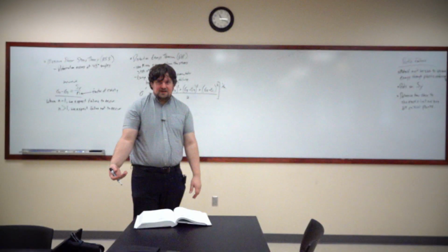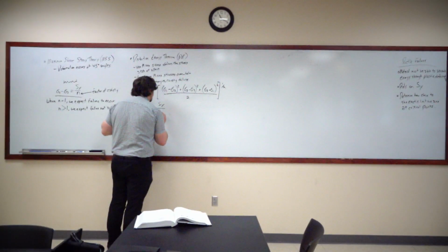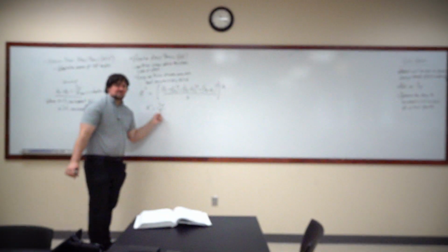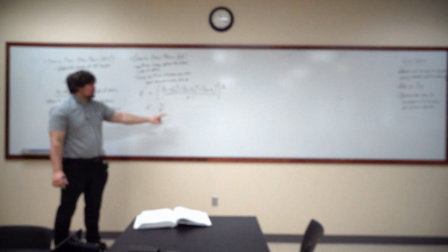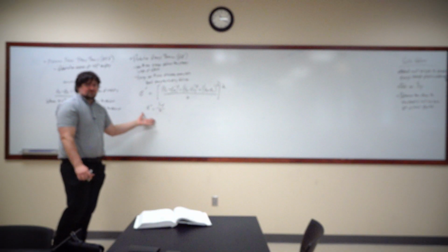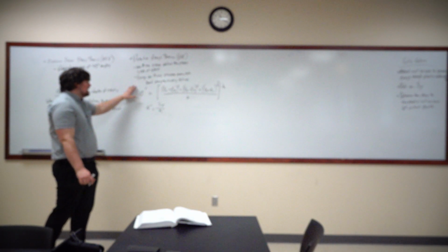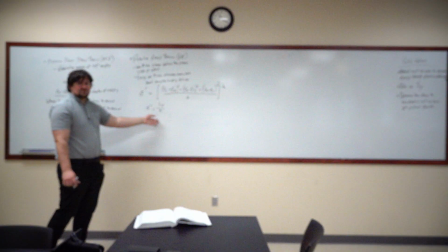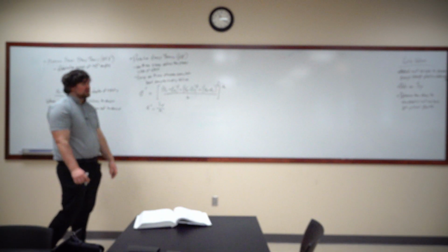Okay, so here's where we have this new stress value, and then this is going to give us our simplest failure condition, which is just sigma prime is equal to Sy over N, where N has the same value. Sy again is the yield strength of the material, and this is now our von Mises stress. Okay, if you can have some solver automatically give this to you, this is going to be your fastest way.